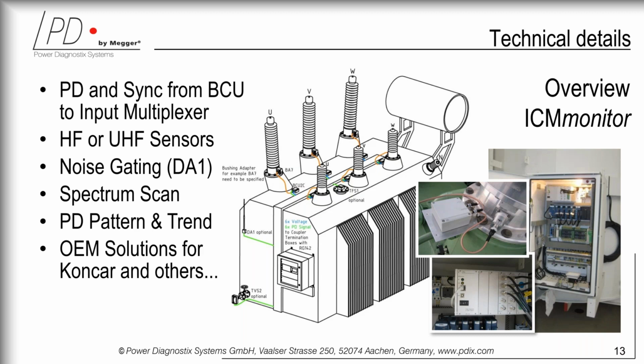There are a variety of companies purchasing such fittings from us because they would like to connect instruments to the bushing. Some purchase them just to be able to read what's happening with the bushing, but most people continue by installing the box that you see here, connected to the Teflon cable. This box is able to split voltage and partial discharge measurements.